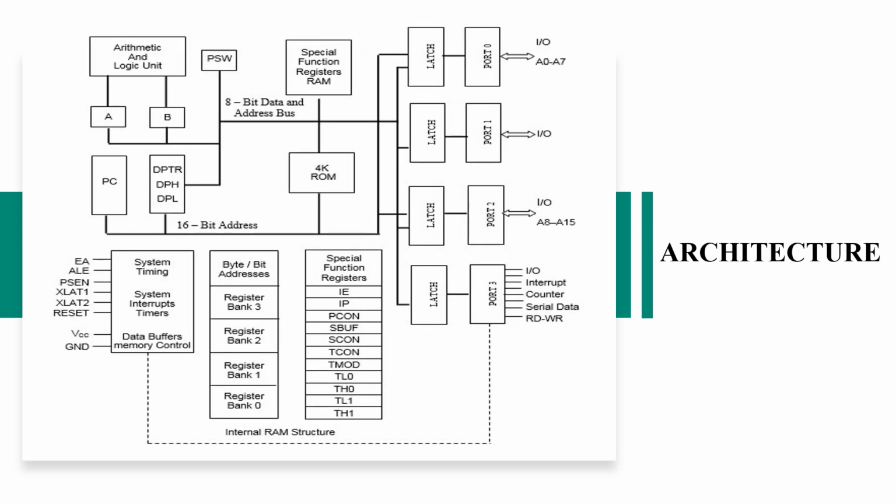So this is the complete architecture of 8051, and the 8051 uses Harvard architecture. It means it has separate memory spaces for program instructions and the data, that is ROM and RAM. Why is this separation required? This separation allows for concurrent fetching of instructions and data so that performance can be improved when compared to the single memory space design, that is, when compared to the Von Neumann architecture.